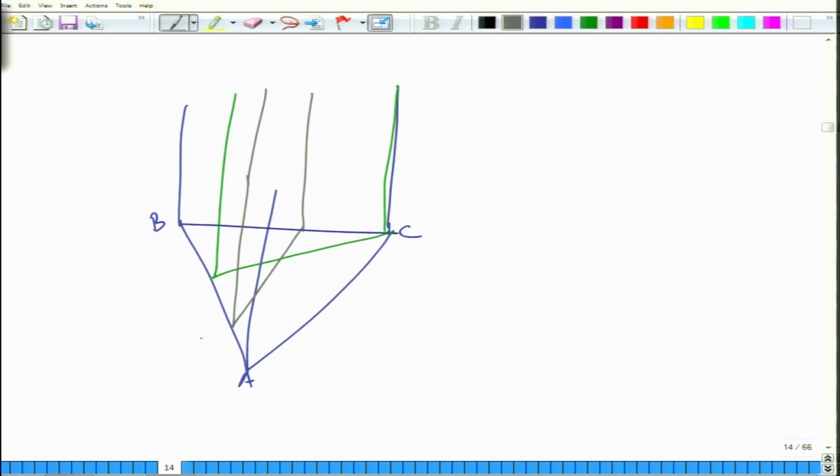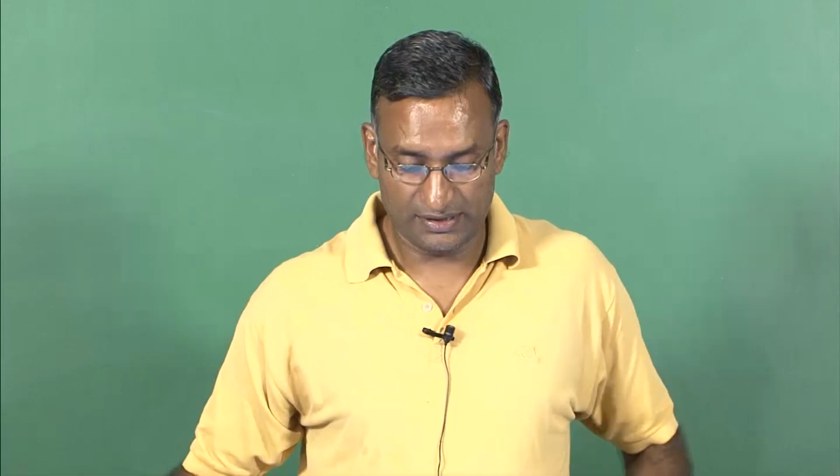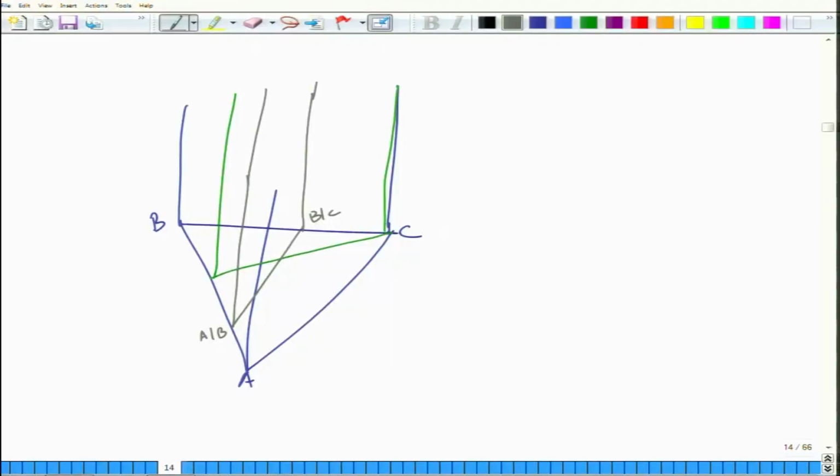So you can see that this has a certain A by B ratio, this has a certain B by C ratio. So you are moving from a certain A by B to a certain B by C, and in between, for example, you will encounter certain specific compositions, and these basically give you evolution of phases as a function of temperature along this line. So along this line of composition you see the phase evolution as a function of temperature. So these are nothing but isopleths.